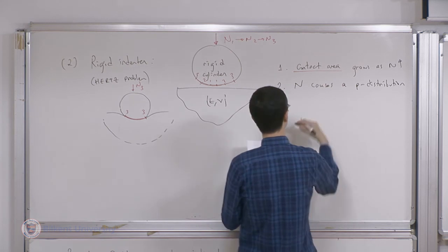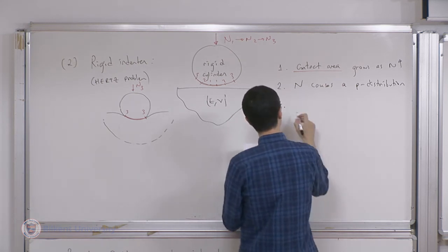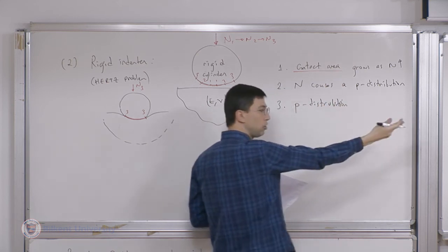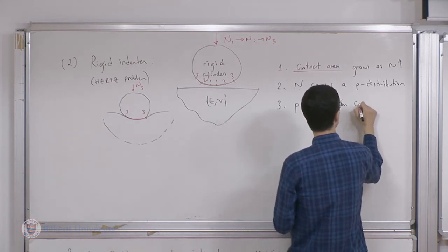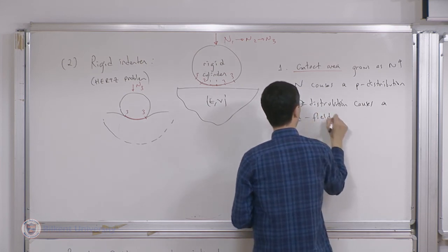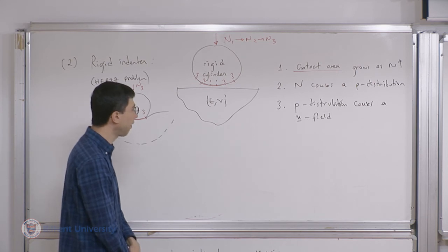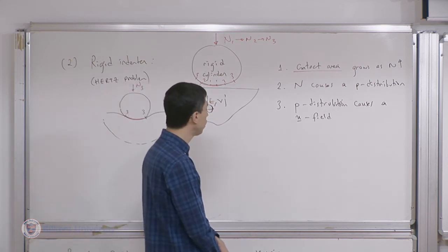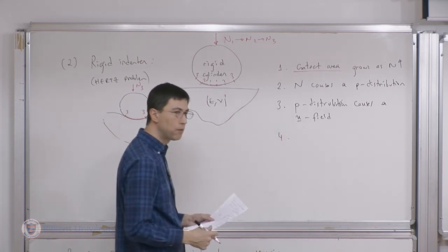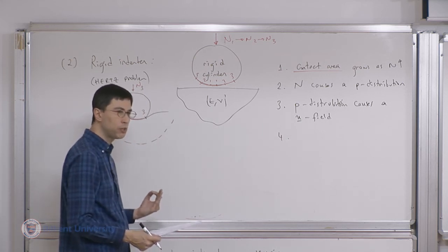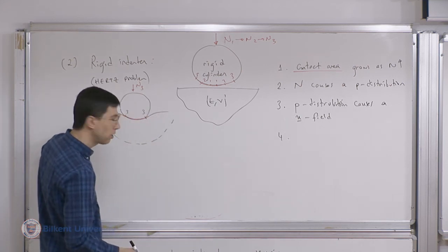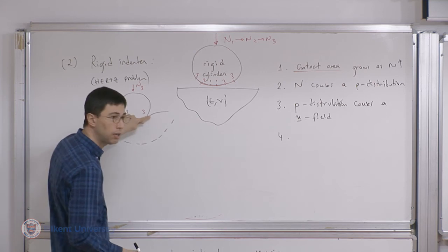There could also be a tangential one. Let's just focus on P. So the pressure distribution, if I know what it is, it causes a displacement field that I could easily solve based on the capability that I already, in fact, have. So the P distribution causes a displacement field, okay, which I could solve through this superposition idea. And then, however, this displacement field is a special field. It is not any field. It is such that the displacement where there is contact conforms to the geometry of the cylindrical indenter.